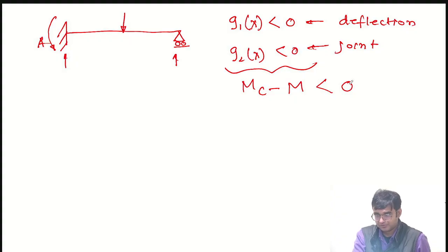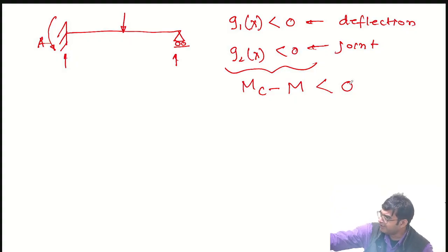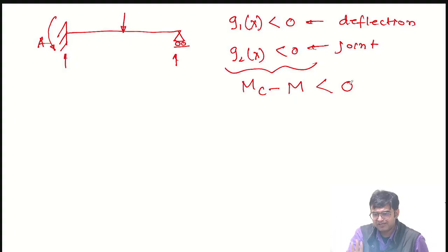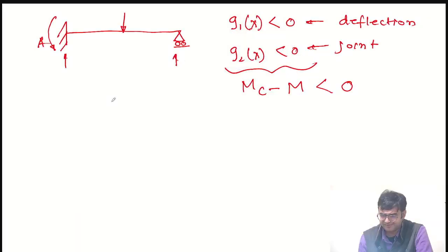Right? But that joint was not only supposed to carry moment, that was a fixed joint. Moment was one of the degrees of freedom, or one of the things it was restraining. There were other things it was restraining. What was it restraining? Forces in two directions. The other one I've not shown. But what happens when I have a fixed joint that cannot carry moment? What do I get? Simply supported.